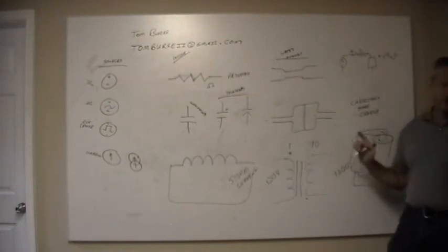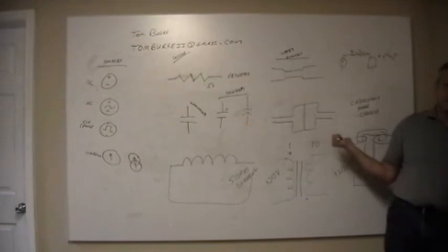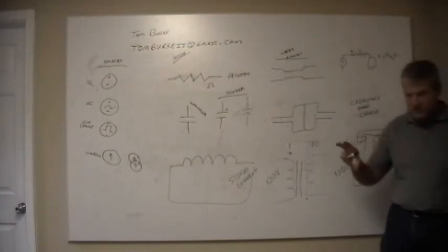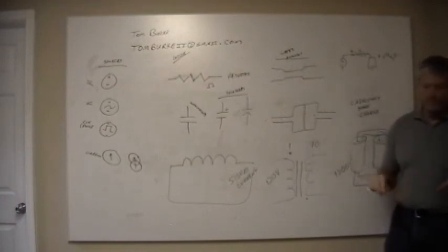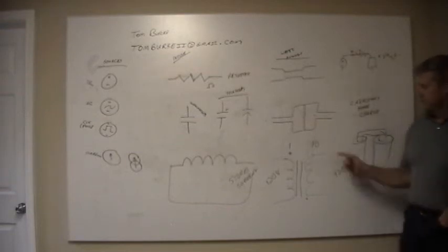A really good, you know, I go to some vendors every now and then that have transformers made for my work, for what we do. You can get up to 0.99 efficiency, tuned at a specific frequency, at a specific load, but 0.95, 95% efficiency is a good number. 96, 97, somewhere around there is about what you usually see for a good iron core, well made.